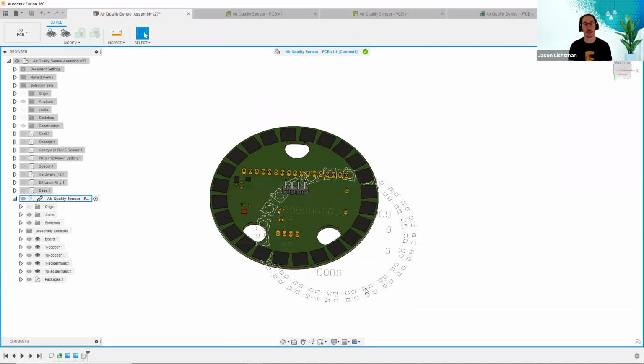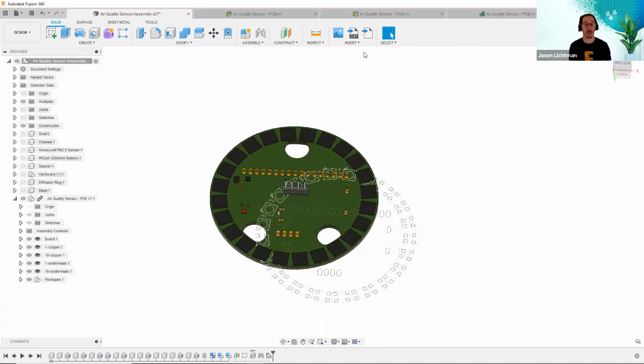And the reason behind that is because the origin of a PCB is typically the bottom left corner of the board. And if you change the size of the board, that origin moves. The silk screen is related to the origin, so of course everything is a little jumbled, at least temporarily. The key though is that I made the changes to the board. Now I could go and push those changes to the 2D board layout. And when I recreate that board, it's going to update everything for me automatically.